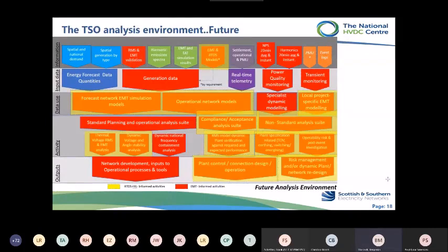the world changes. And the world changes because if we take the example of the offshore AC grids, there's no inertia. There is a power system control response. There is no short circuit level that's inherent. There are controlled fast fault current injections during a disturbance, and there are speeds of response associated with reactive power delivery, which are dictating the strength of those networks.